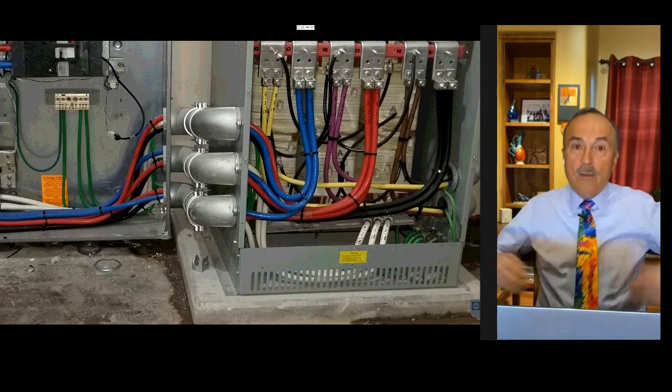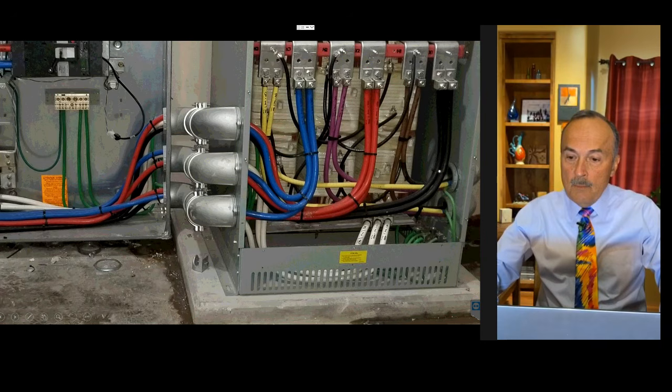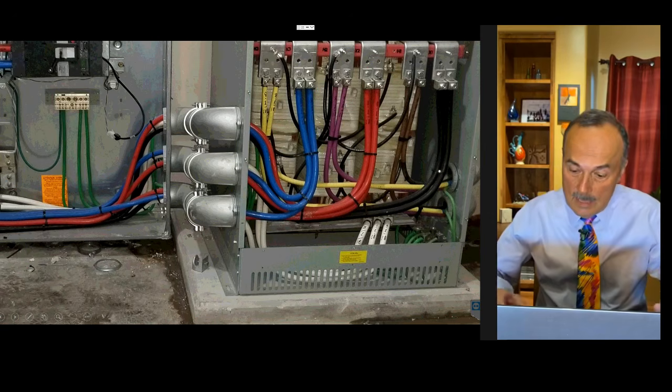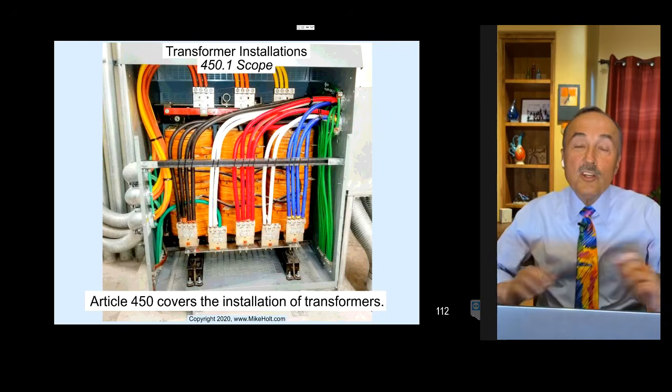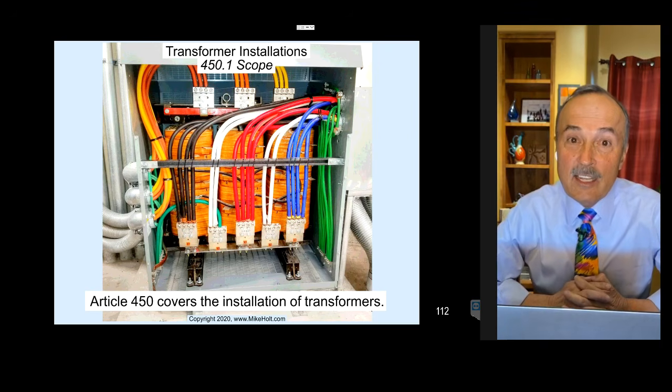All right, back to our graphic here. No bonding bushings, no bonding jumpers. Everything is fine. It doesn't matter the wiring method that you're using. And of course, there's the equipment grounding conductor bar that's required by 250.10(A). I want to show you something. I just had this changed.